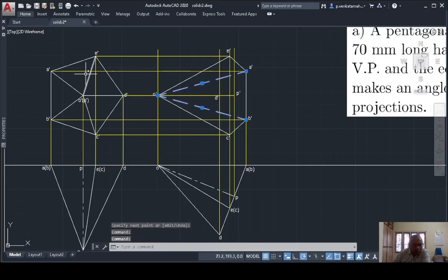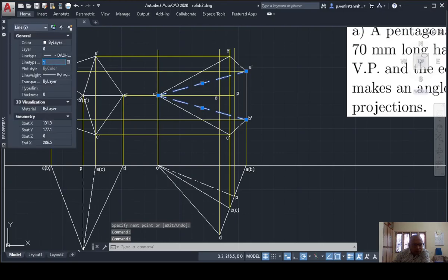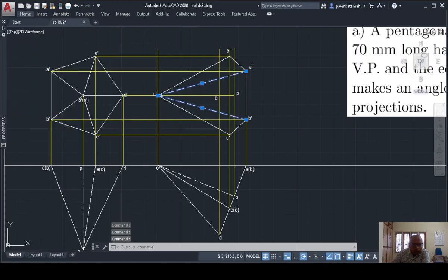So that it is visible. So length type scale 0.5 and keeping so that I get more number of dashes. So this is the hidden lines. So what else is there? Then I will reduce to here so that there is no confusion. And this line also I will reduce so that clarity will be there.